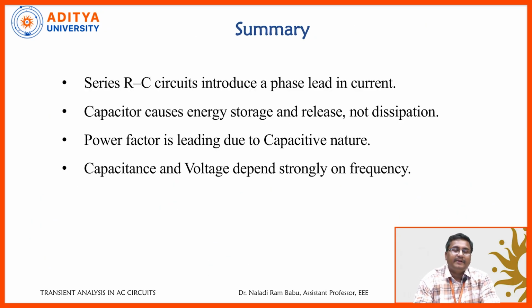Now coming to the summary, we have done series RC circuit calculations with the help of the Laplace domain. Here, because of the capacitance, the current leads the voltage. The capacitor is the element that is used to store and release energy. The power factor in the RC circuit is always leading in nature. Here the capacitance and voltage values are strongly dependent on frequency.